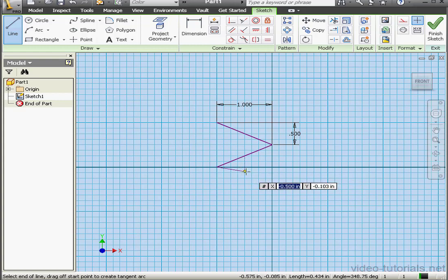Notice the pound or number symbol that lets me know I'm in the absolute method. There's the origin point, 0 on the X and Y axes. For my values on the last point, I'll enter -1 and 0. Let's enter another coordinate, -1 for the X value, tab, and 1 for the Y value. Tab to register, press Enter.